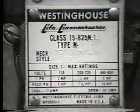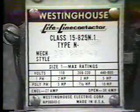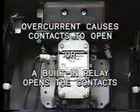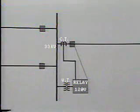Another type of protection frequently encountered at utilization voltage of, say, 480 volts is the direct acting contactor. In one common type, overcurrent causes thermal contacts to open the circuit. In another type, a built-in relay opens the contactor. However, let's return to the thrust of this program, that is, protective relaying of the power system.